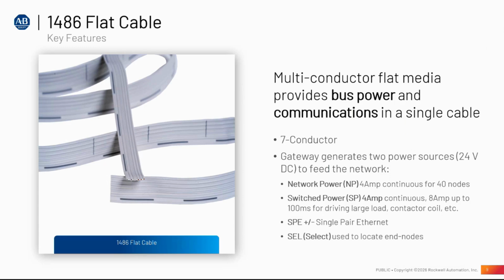The flat media cable is a 7-conductor. This provides 24 volts, which will be 4 amps continuous, or up to 8 amps for about 100 milliseconds when a contactor turns on and you have that instantaneous inrush current.